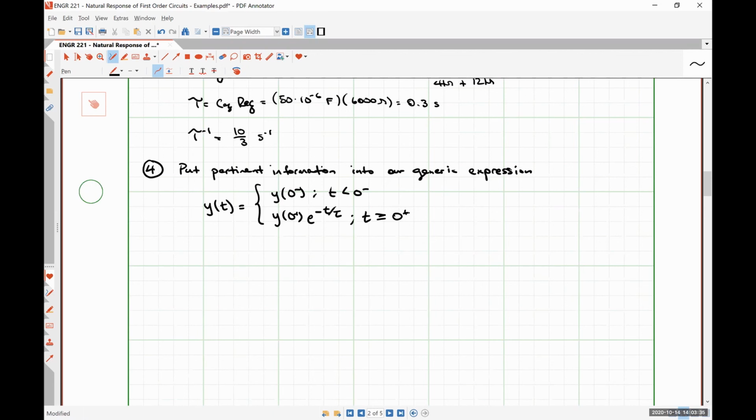So how and why this works is, if you've watched the video, I derived how everything worked for, say, the voltage drop over a capacitor. Well, Kirchhoff's voltage law is going to tell us that if one voltage has this exponential response, then all of the voltages have to have that same exponential response to be able to add up to 0. And then Ohm's law tells us that then all of our currents will also have that exponential response. So let's look. That is little t representing time divided by tau, which is our time constant for our circuit that describes the exponential decay.